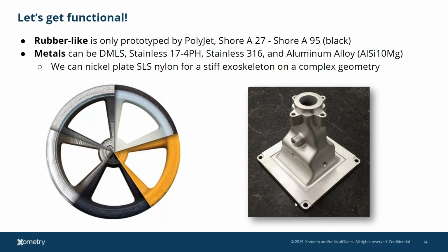We can also do some things. So if you're talking about something that needs to be metallic, or maybe it's metallic because it has an EMI requirement, we can nickel plate materials like SLS nylon. What it does is offer mechanical stiffness, so it makes it about 5x stiffer. And also it does have some EMI shielding effects as well. So I usually see that used for both of those. But just understand that it's not a chrome plate. It's not a cosmetic look. It is a matte nickel plate finish that adds a mechanical attribute, a mechanical function.